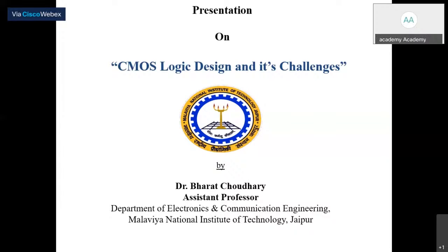One is asking a question, let me clarify whether TFET is better or FinFET. TFET has its own advantages and FinFET has its own advantages, so you learn both and compare. TFET is suitable for ultra low power applications, but its on current is less in the architectures. So researchers are investigating how this on current can be improved.